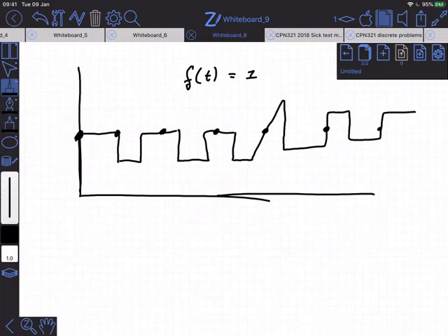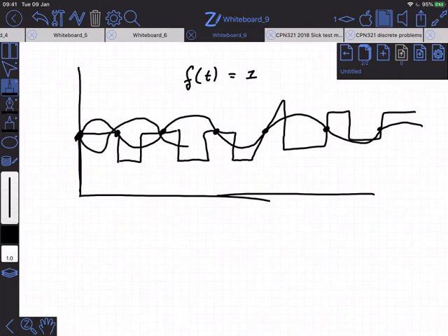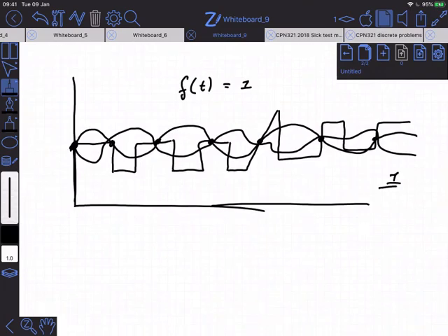They don't have to be discontinuous. They can be continuous. And so every single one of those functions, if you go crazy, you remember every time you draw a line, you're drawing a function. Any function that is 1 at all of those points will have that exact same z transform. Its z transform will be exactly 1 over 1 minus z to the minus 1.